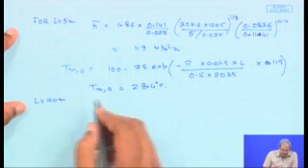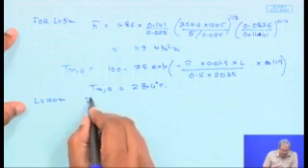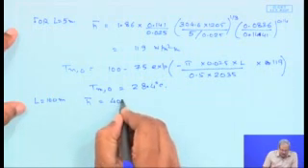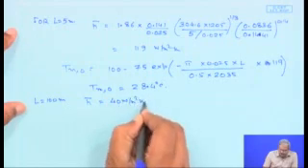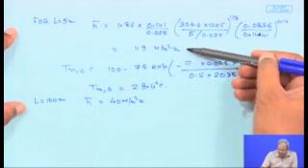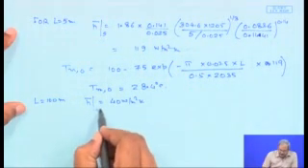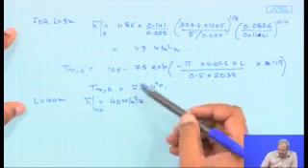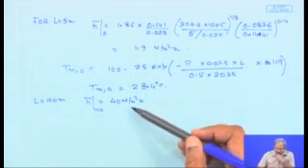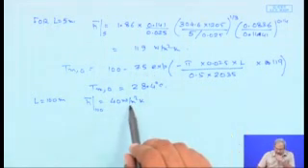In a similar fashion, I am not doing this again. The L equals 100 meters, the H bar that you are going to calculate is 40 watt per meter square Kelvin. So compared to the value of H bar at 5 and this is H bar at 100, you see the difference. You see how the average value reduces as the length is increased.